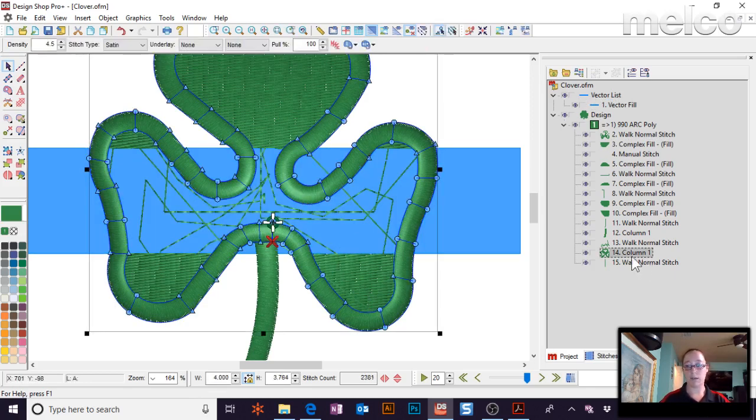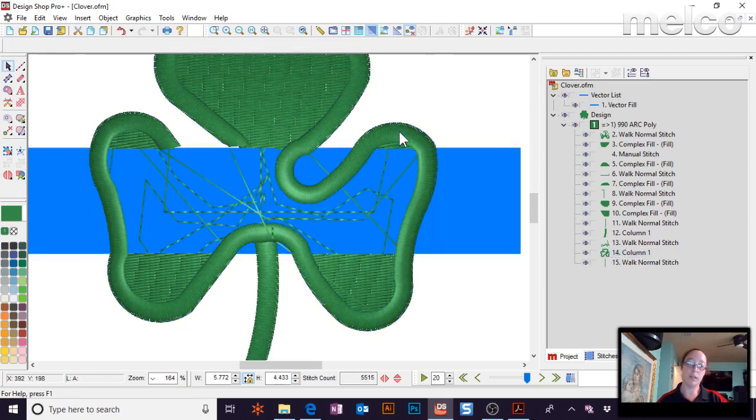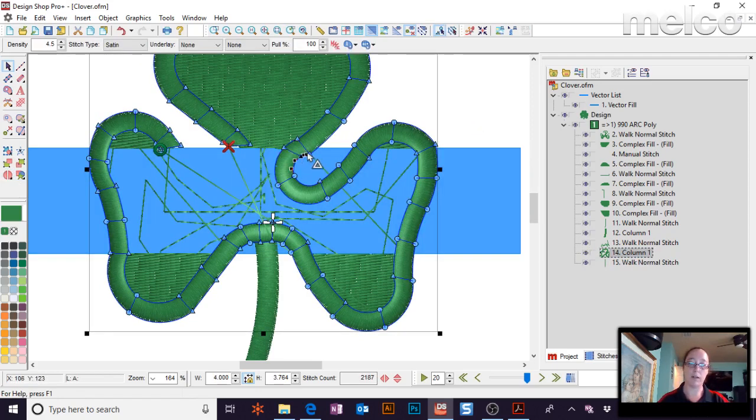Now what about this? This is a column. You can tell that, it says it over here. This one we have to do a little bit more work on because it keeps on intersecting this line a bunch. We want stuff that's outside of the blue box, right? So here we've got to kind of work our way around splitting the element. So I select one side and I say split element. I'm going to come over here, add a point, and again say split element. So now I've got this in the middle. So now I can just hit the delete key on that. And again, just work your way around there,